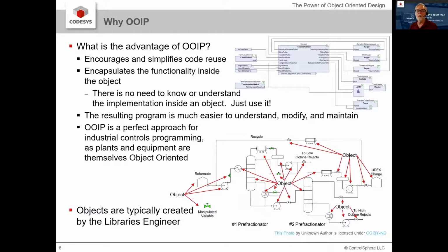All right, object-oriented industrial programming simplifies the design of your plant or equipment and makes it much easier and much more likely to reuse control objects on future designs. Your plant or equipment is made of objects: motors, actuators, sensors, whatever. The control of your plant or equipment should be made up of objects too. So just as a motor is a completely self-contained object which does not require assembly or modification, the control for that motor should be a self-contained object which does not require assembly or modification.